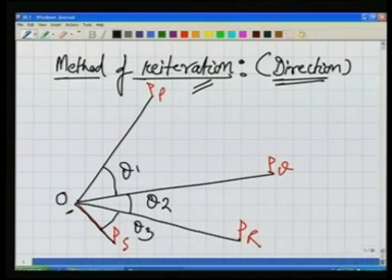What do we do in this case? The procedure is simple. Again, we will take our theodolite to the point O. The theodolite is set at O. We will make the reading in the theodolite 0 degree, 0 minutes and 0 seconds. You know how to do it now. Once we have done it, we will unclamp the lower screw and rotate the theodolite or the telescope. By unclamping the lower one, while the upper one is clamped, the reading is not changing. It still remains 0, 0, 0.